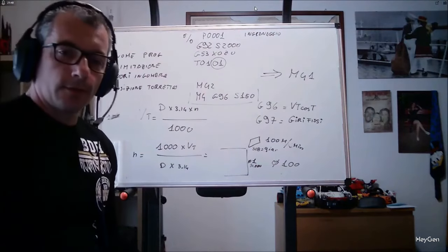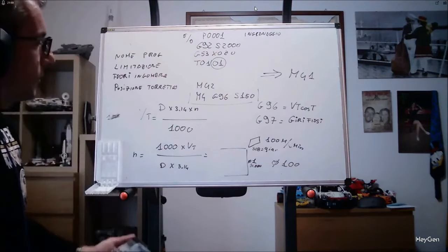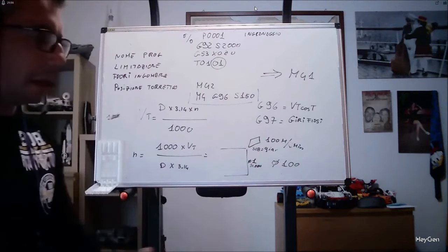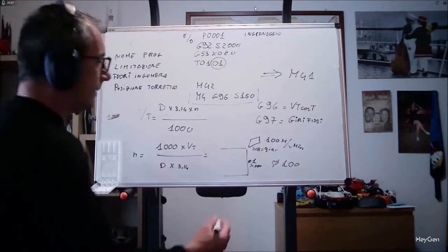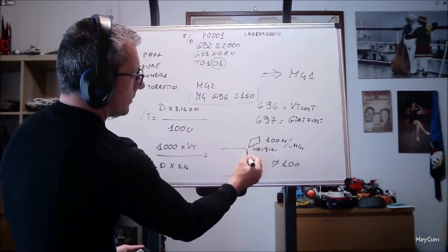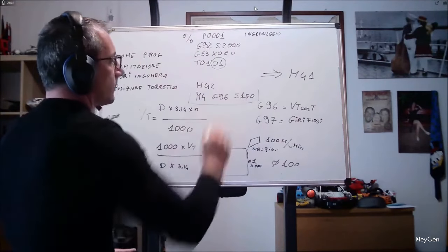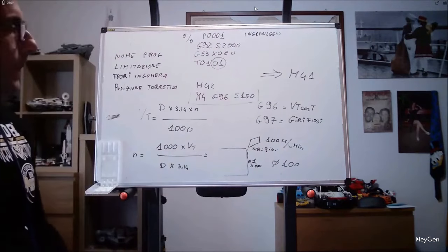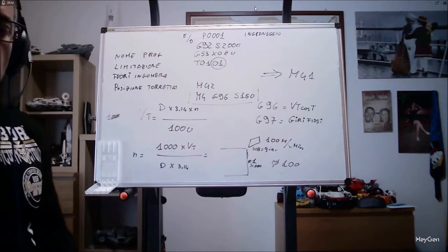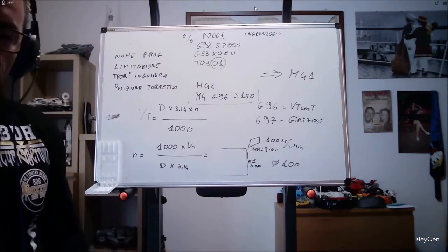It is quite obvious that a lathe, perhaps of large size, at 31,000 revolutions, will break apart. You will find screws on the ground. That's why the machine will slow down. It will increase its revolutions as it approaches the center until it stops here. Here is the difference between constant cutting speed and fixed revolutions.